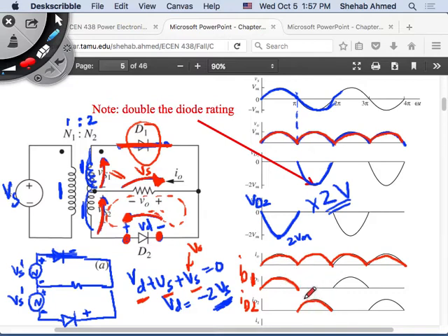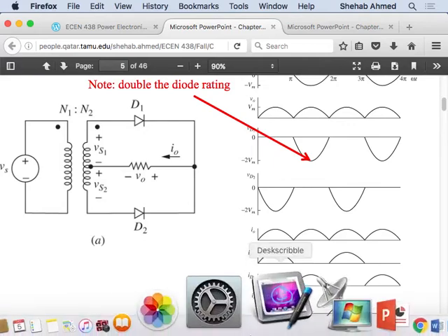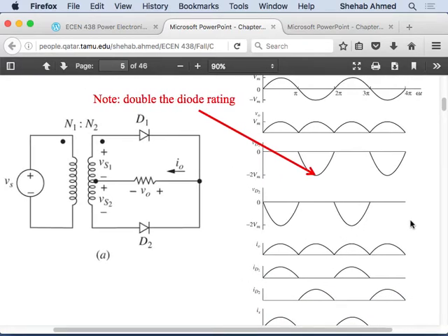How about the supply currents? Also sinusoidal. It's also a sine wave because in the positive half cycle this supply is conducting, and in the negative half cycle this other supply is conducting, and we flipped the source. Since I flipped these sources when I derived the negative half cycle, it's like I have to flip the input source symbolically. So you will see that the current will also be sinusoidal in this case. Any questions on this circuit?